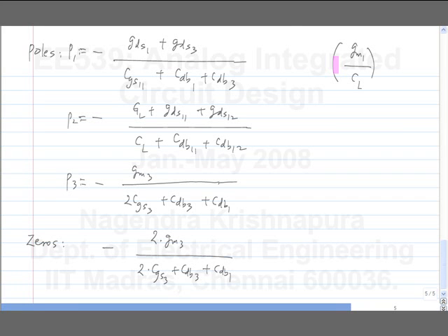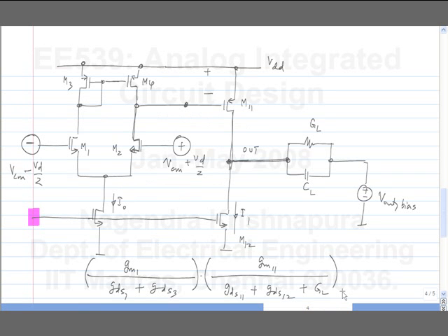I think we already know the solution. We have discussed the common source amplifier endlessly before. How will we do that? Yeah. So that's not by creating a zero, right? We are doing pole splitting. Because that zero is in the right half plane. It in fact worsens stability. Right? It doesn't enhance stability.